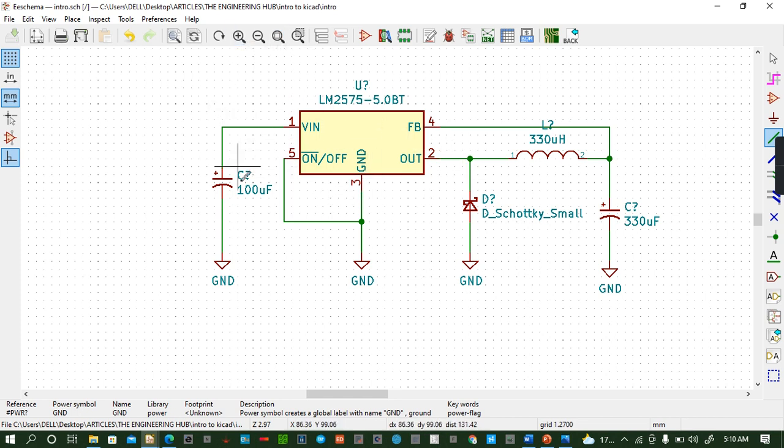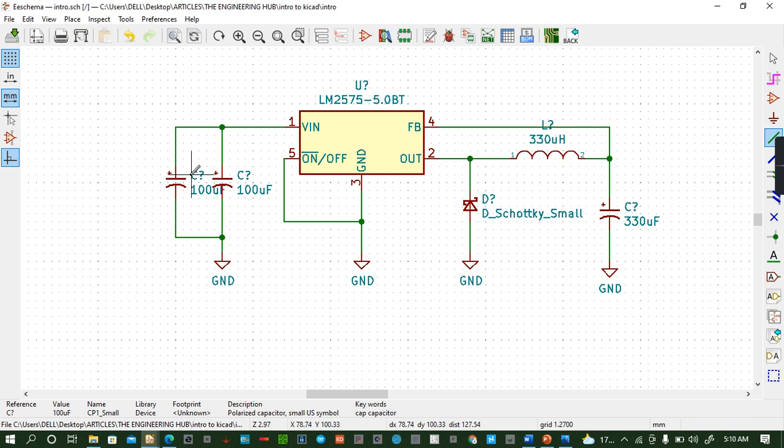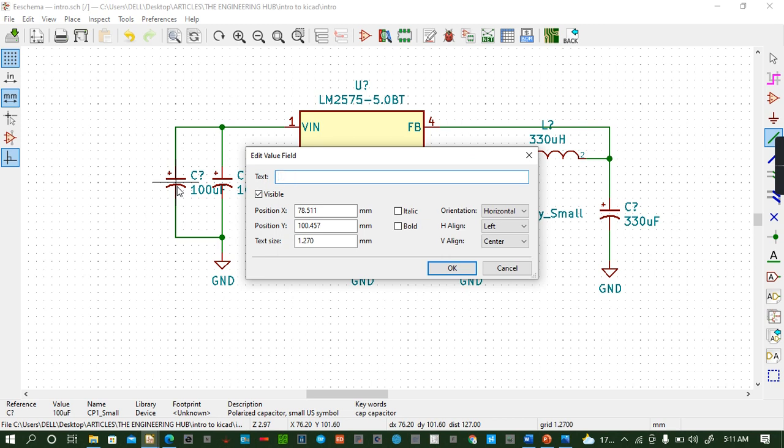But I want to add some capacitors. You know, the more you add, you filter the signals, the more the signals are free of noise and vibrations. So I can add another capacitor. This one, copy. Place there, then wire like that, then a wire like that. This one I will edit the value and make it 10 UF.